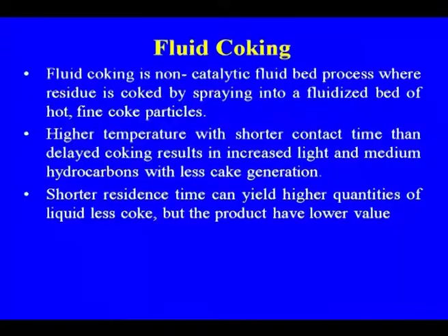Now, let us discuss some other development taking place in the thermal cracking process, that is the fluid coking process. Fluid coking is a non-catalytic fluidized bed process where residue is coked by spraying into a fluidized bed of hot fine coke particles. Here we are using the fluidization phenomena for the cracking process, and as you know, in case of fluidization, there is definitely an improvement in the quality of the product, other parameters are also affected, and there is better operation.